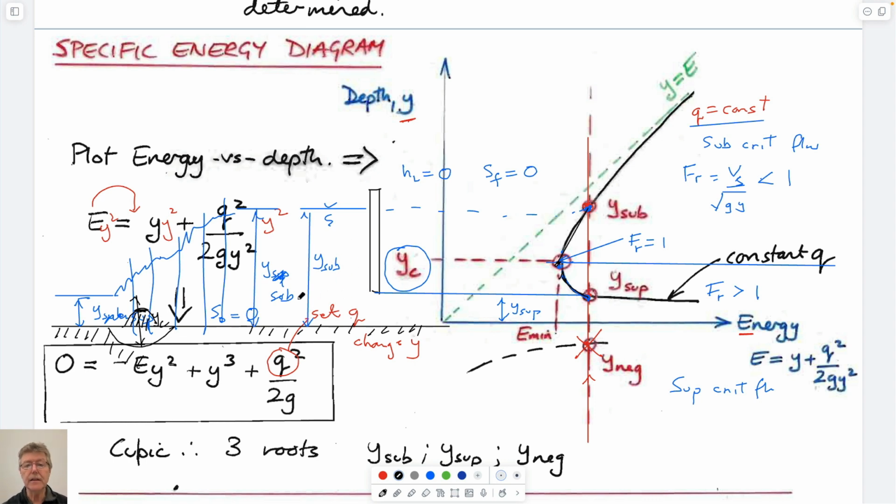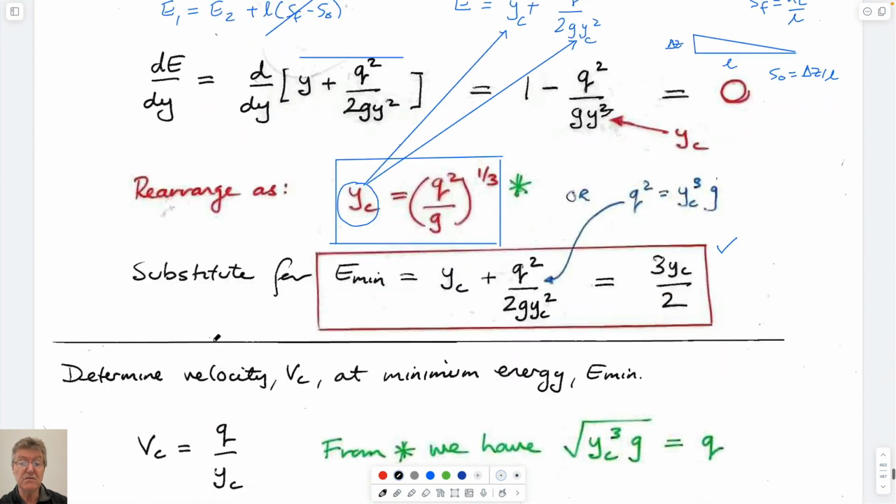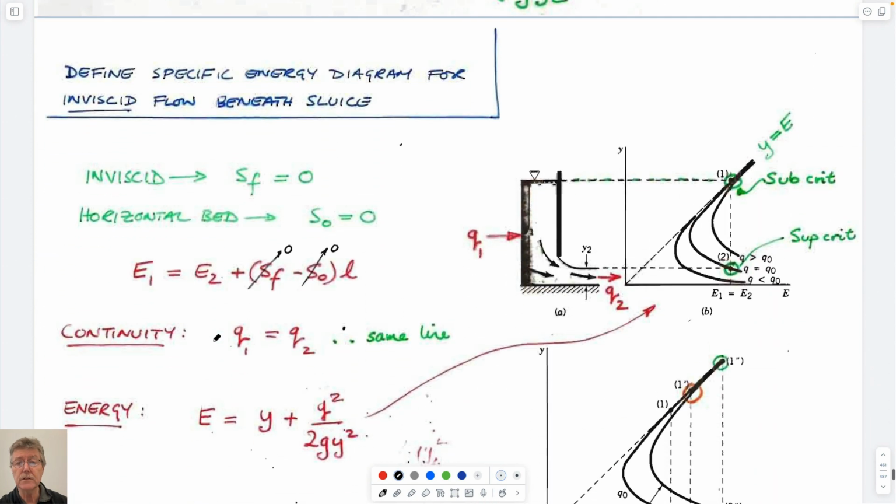And so the idea is that these transformations occur, but if it's the same volumetric flow rate going from upstream to downstream, there has to be something that kicks it over and perturbs the system, making it go from one state to another state, typically as it goes along this curve. Typically it would be a change in the bed, although you don't really see it in that video. There's no apparent reason for that. And so that's how you might change from one upstream behavior to downstream.